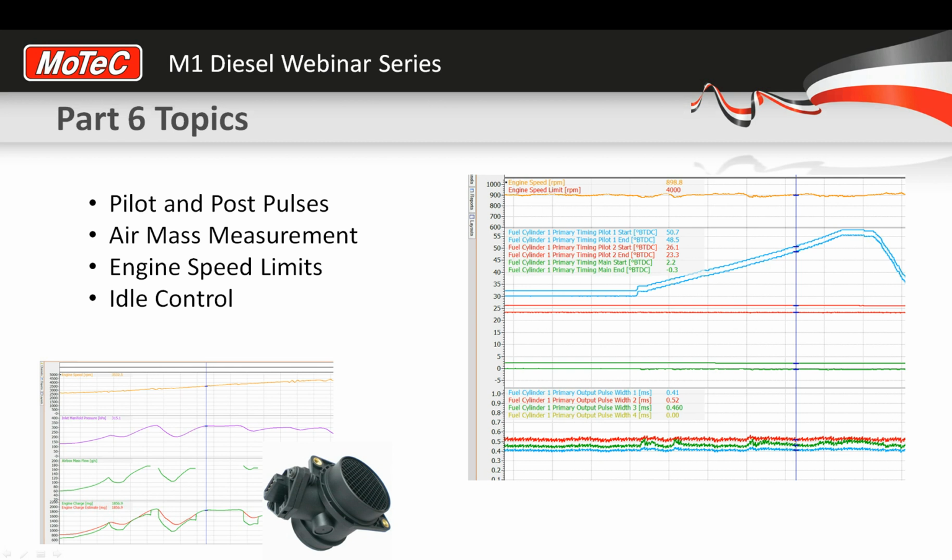So topics for today. We're going through pilot and post pulses. We've talked about those in previous webinars, but just a little bit more in depth and just to reaffirm what you've learned so far. Air mass measurement, so airflow meters and the channels that are involved in the ECU to do with that, and how to scale up to a larger airflow meter if you're going to fit something different. Maybe take an air mass meter element apart and put that element into a larger pipe. So we'll cover off how to do that and how to change the calibration.